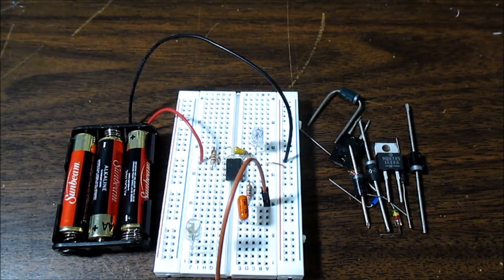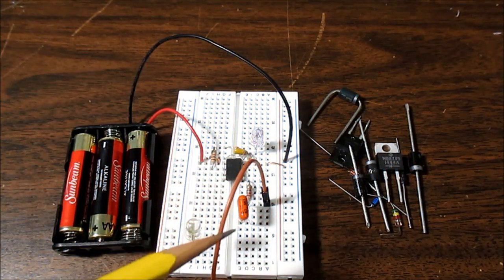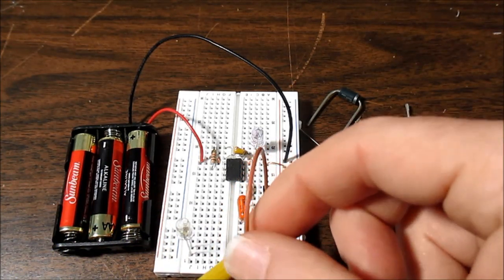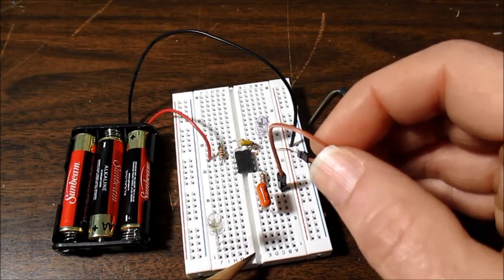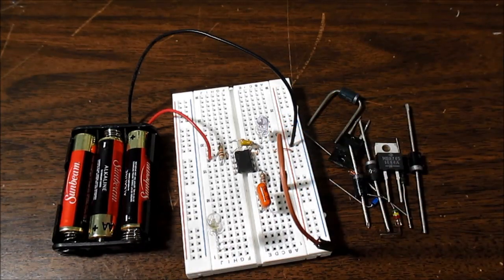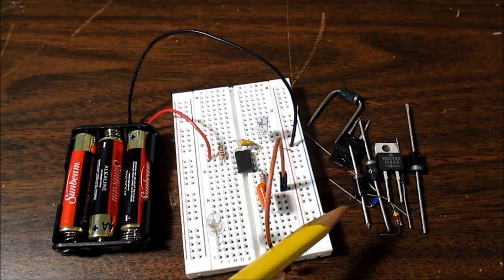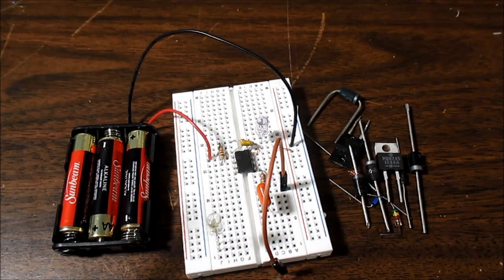You have to use the probes in 10x mode, and I have to keep these wires short. First I tried using alligator clips, and the length of those leads had extra inductance in it, and it was causing a lot of ringing on the oscilloscope screen. So I'm just using this little lead here, and I'll just have to hand hold the diode and get a reading off the scope. Okay, I'll point the camera at the scope while I'm doing this and announce what device I'm testing.